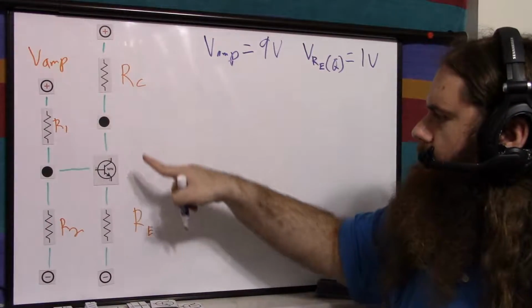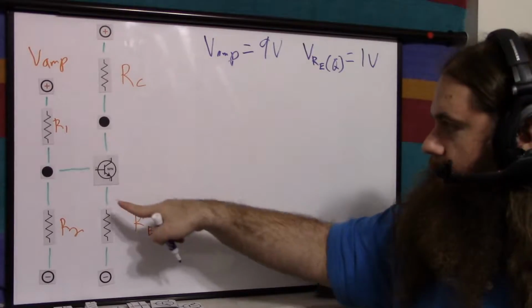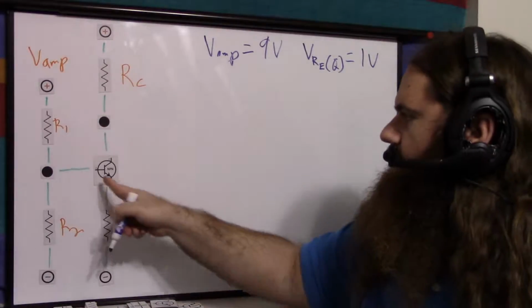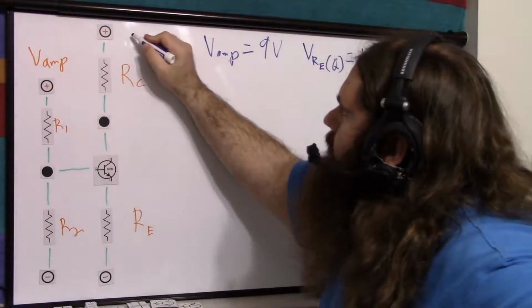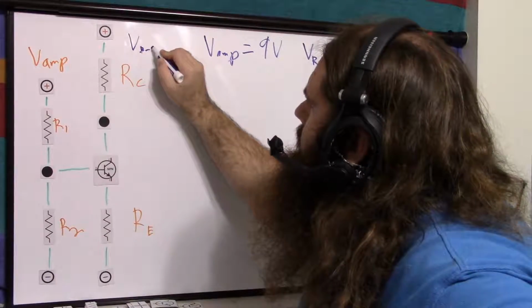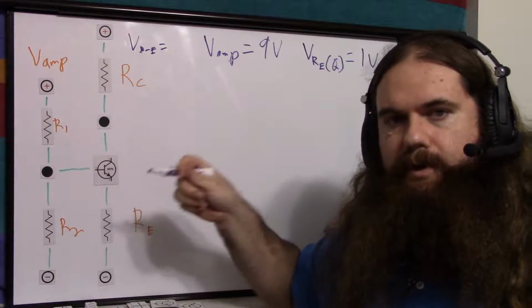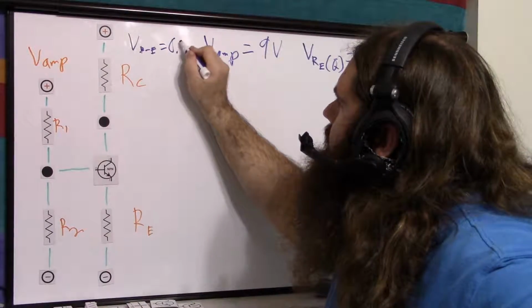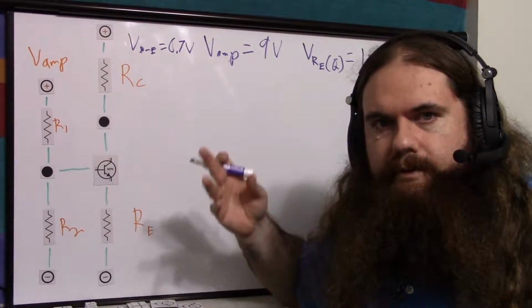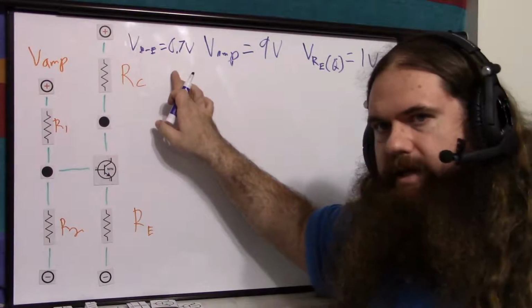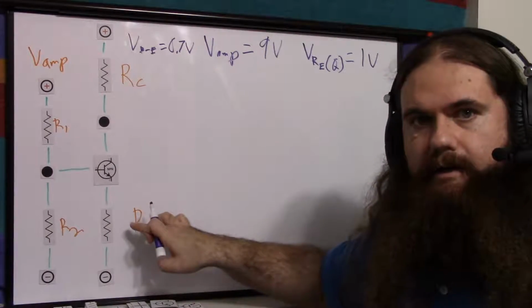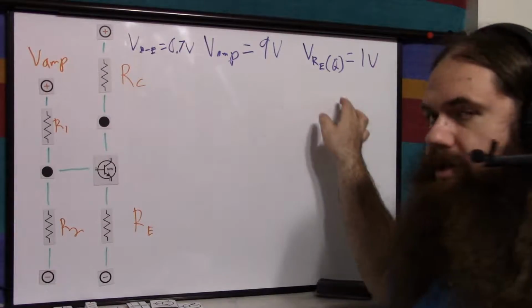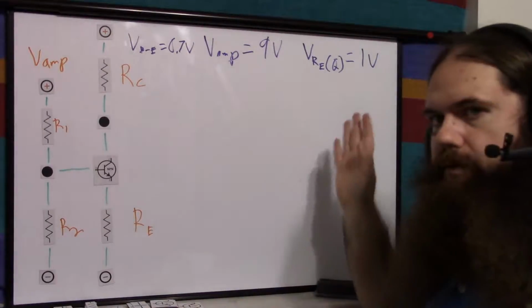So that's 9 volts, and at quiescence, this is going to be 1 volt. Then we decide on the base to emitter voltage. So voltage of base to emitter. This is just the standard approximation we use for diodes and transistor bases. We'll say 0.7 volts. Just a standard number. You can use it everywhere. It's good enough. If it's not exactly that, that's fine because RE gives you wiggle room. So these are just the things you decide on. Just go for rules of thumb.